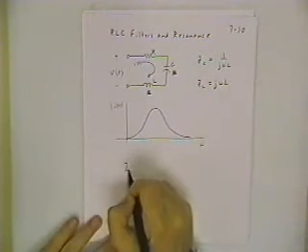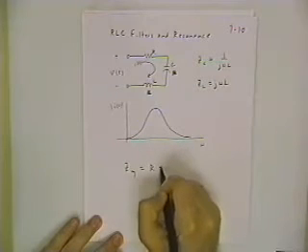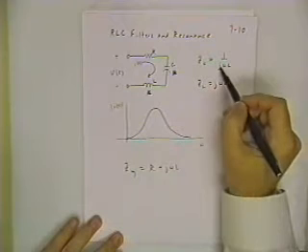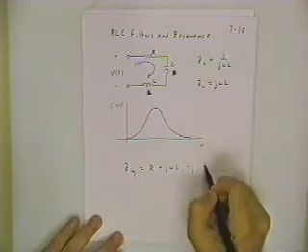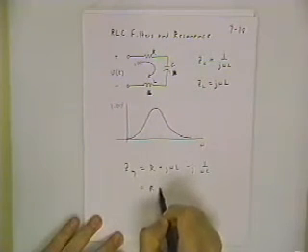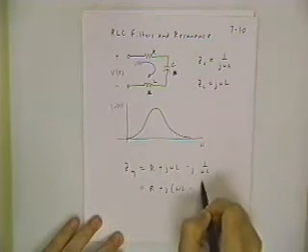You get a Z equivalent equal to R plus j omega L. And now if you'll let me put the j upstairs, that makes this a minus j 1 over omega C. Now you can get a hint of what's happening.